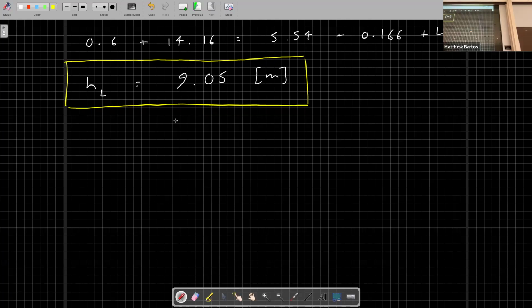Widen the channel, possibly. You mean within the transition? I'm not sure that's right. I would have to look into that. Let's see, if it's subcritical to start out with and you widen the channel, it would result in an increase in the depth.